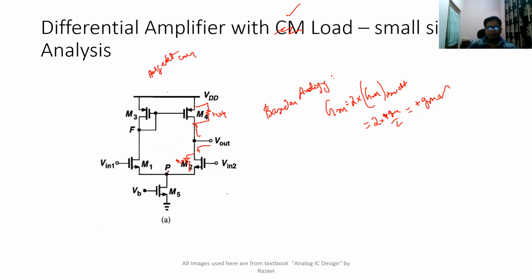This P can be grounded. Once you ground this P and consider only the half circuit present on the left side, on Vout you have on top a resistor RO4 connected to ground. Below you have another resistance RO2 connected to ground. So when you see it from this side, Rout will be simply equal to the parallel combination of RO2 and RO4.